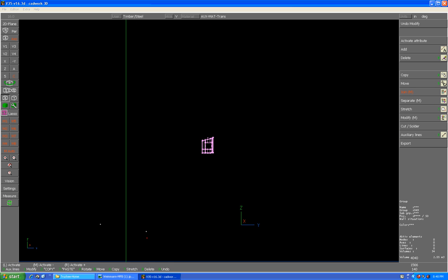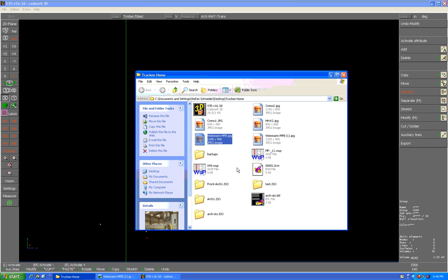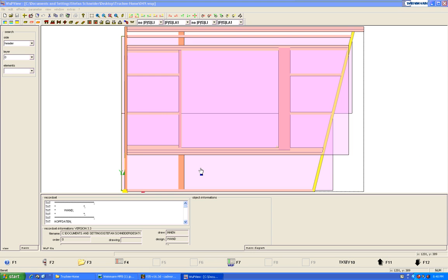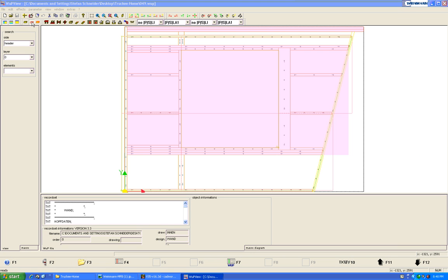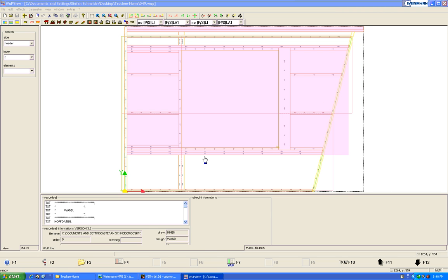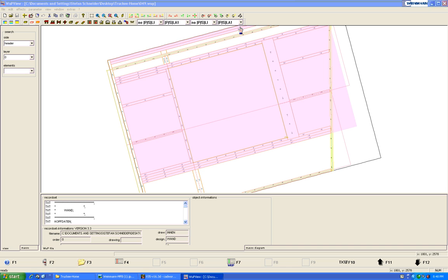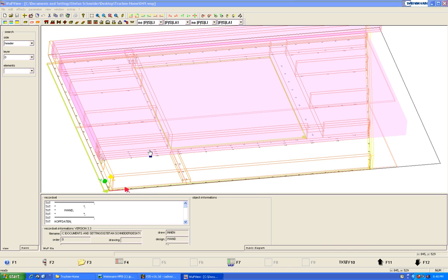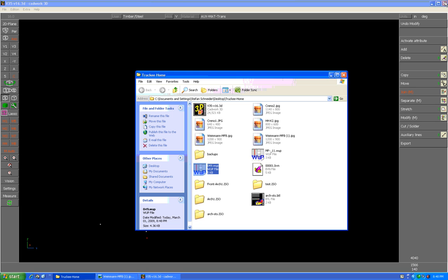I got that NC file now, which is a so-called WUP file. So I go in here, and I will have this wall on my machine. It will show me all these nails. Every point here is a little nail. You'll see around the window opening, I have a closer nailing pattern, and so on. So this is basically the export for these wall lines. This panel here is again produced on that line. We got 3D data here as well, and the blockings are in. So I don't need to do a shop drawing for any panels.